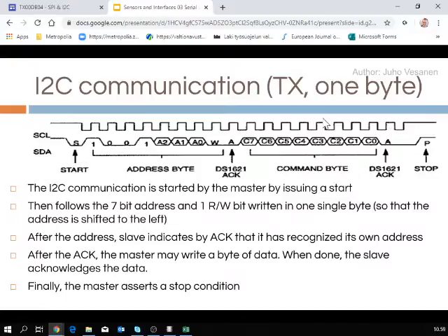Okay, and it either listens to the data or writes the data according to this serial clock. And after every byte, there is an acknowledgement on the receiving side. So if the device is getting the data, then it acknowledges, okay, transmission done. This way you can continue writing to the same device, a data burst.